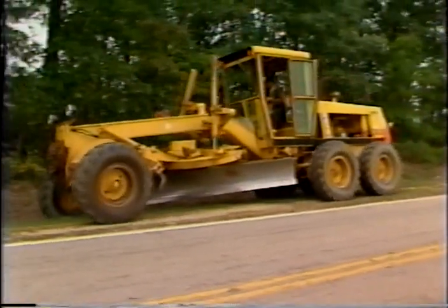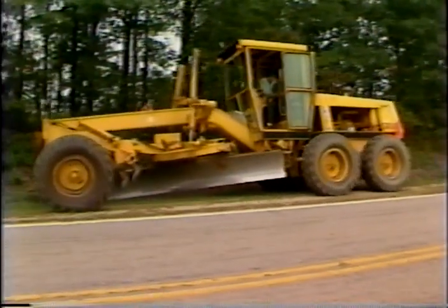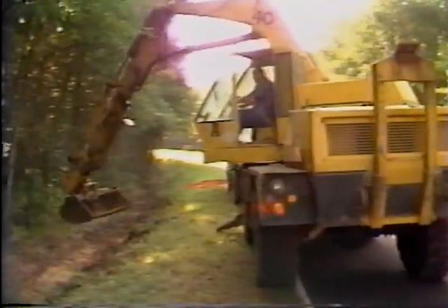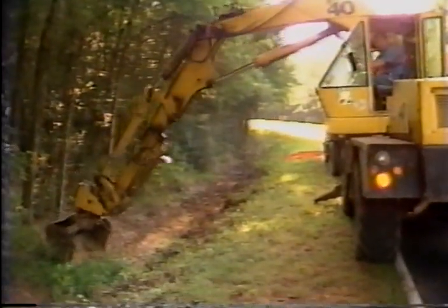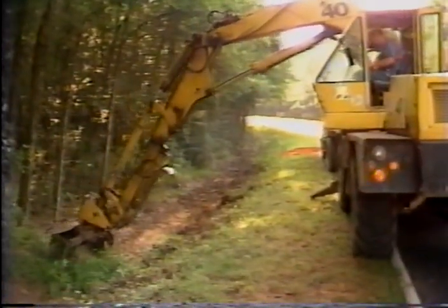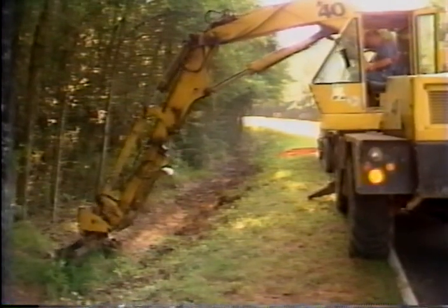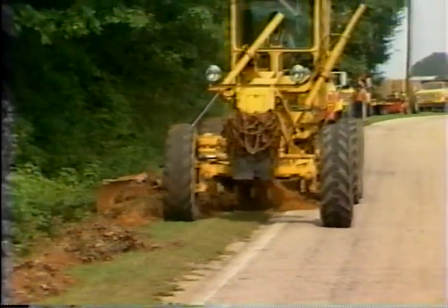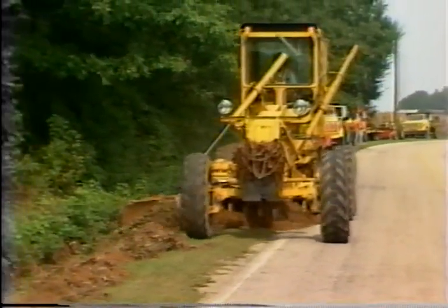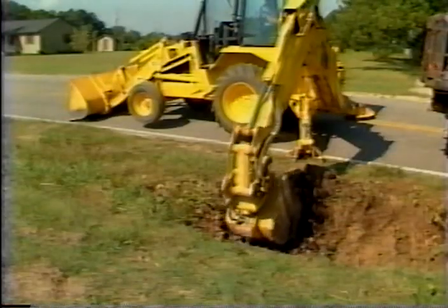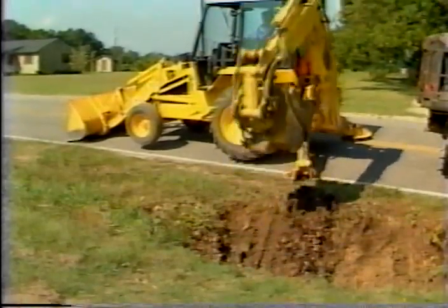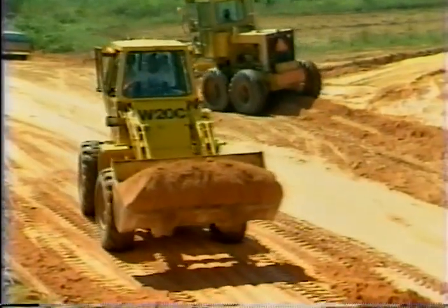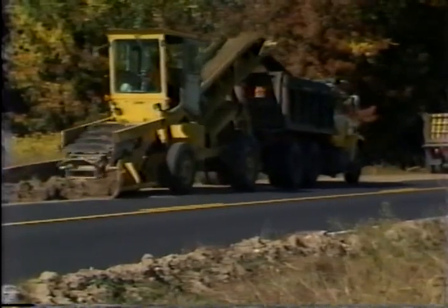There are two primary pieces of equipment that are used to perform ditch maintenance. They are the motor grader and the hydraulic excavator. The appropriate piece of equipment to be used is determined by the area where ditch maintenance is to be performed. The width of shoulder and amount of material to be removed is considered when selecting the piece of equipment. Other pieces of equipment that are used in ditch maintenance include a backhoe, a front-end loader, a belt loader, and dump trucks for hauling.